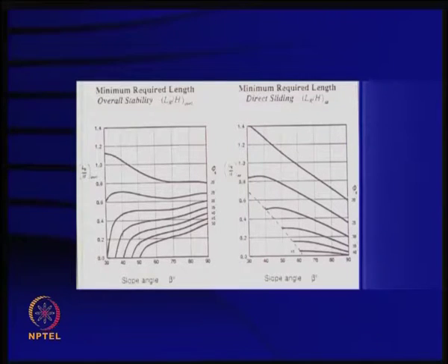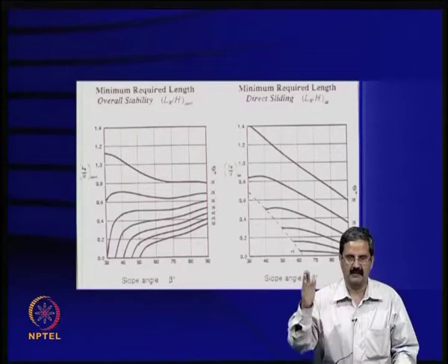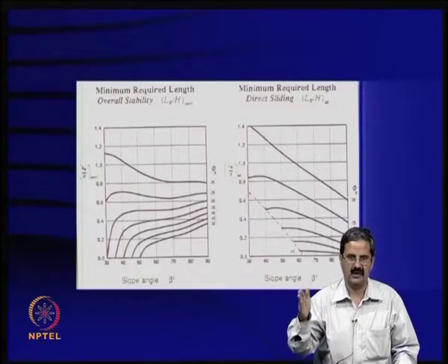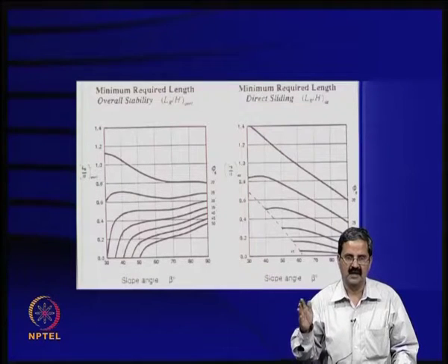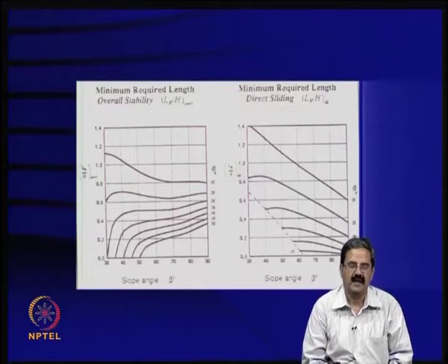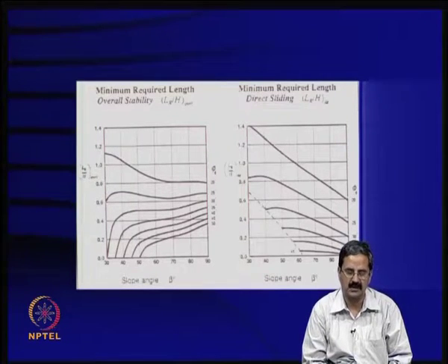One can use a log spiral failure mechanism, one can use a wedge mechanism, or one can use a two-part wedge with two wedges, because it is much closer to what people have observed in the field. Why these failure mechanisms are assumed is that they are noted when there is a failure.